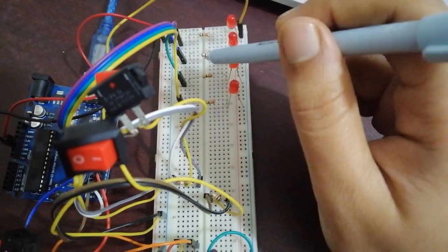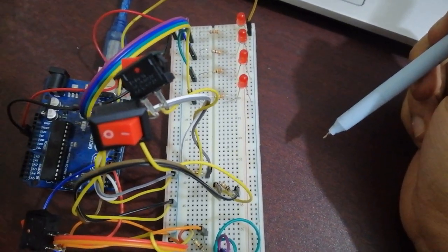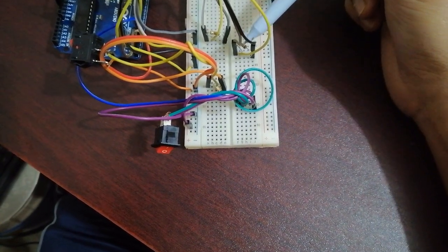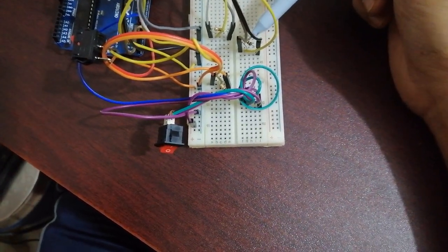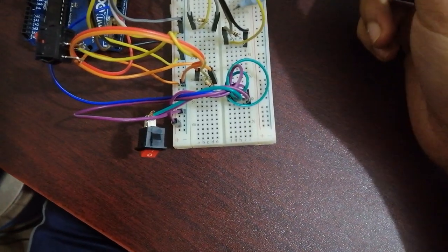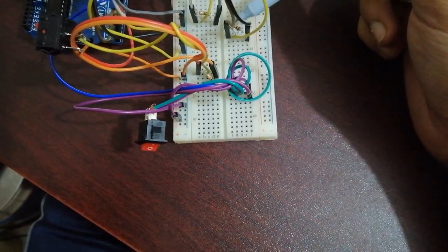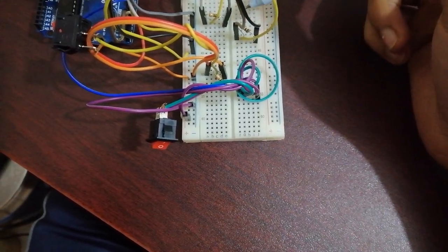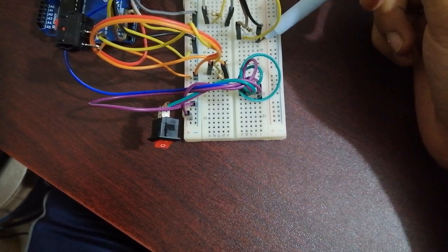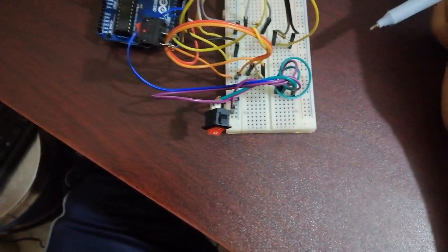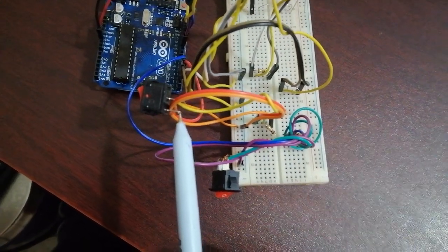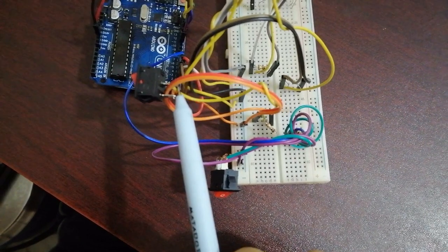Here we use 4 330 ohm resistors on our output side to control the overflow of the voltage, and here we use 4 10 kilo ohm resistors on our input side. Here the resistors, one leg is connected with the 5-volt and switch in series, and another leg is connected with the ground. To build the switch, one leg is connected with the 5-volt and another leg is connected with the breadboard.